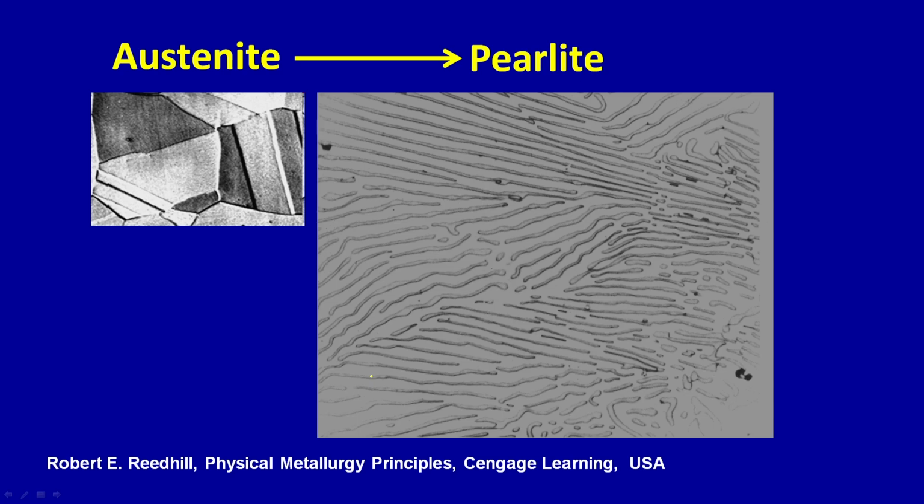So, pearlite is the classical example, everybody knows, very clear, even standard books teach it very widely. So, austenite to pearlite transformation is the simplest one to understand. The diffusion controlled transformation, diffusion of carbon is the main factor, and it leads to a lamellar microstructure, and by controlling the lamellar thickness you can control the mechanical properties, very clear. Martensite is different, it is a body centered tetragonal structure, and it is basically much harder than pearlite.